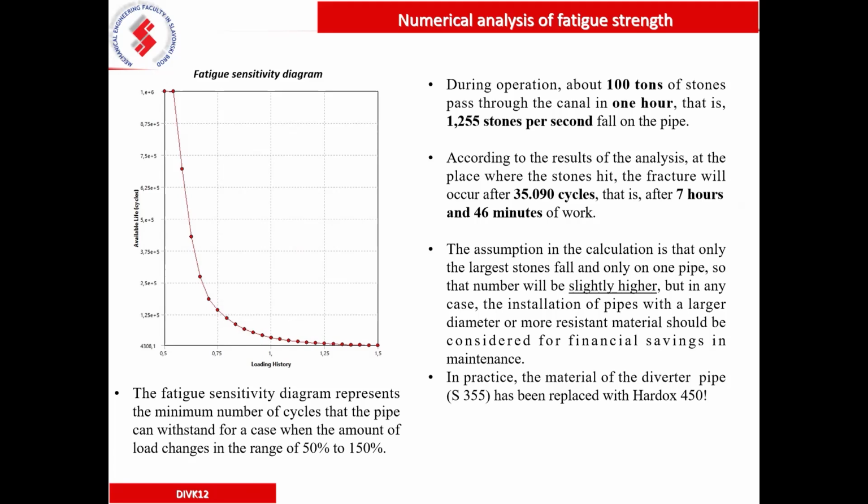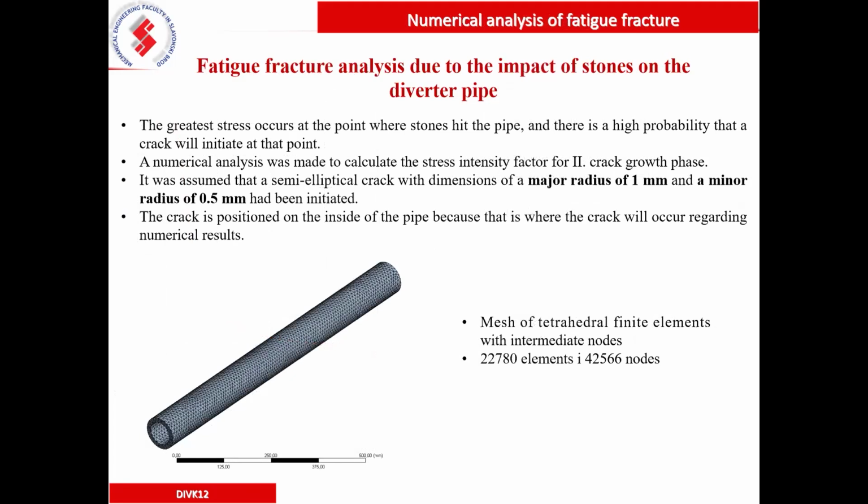Okay. So we also did the fatigue fracture analysis, because we supposed what would happen if we have a semi-elliptical crack with a major radius of 1 millimeter and a minor radius of 0.5 millimeters, which has been initiated at the place where the stone is hitting the pipe. And